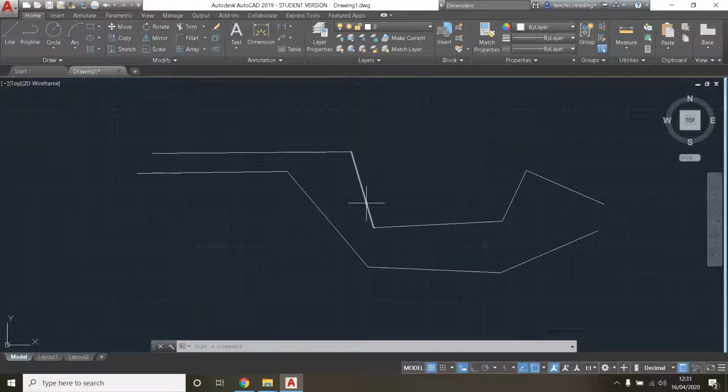Most often you'll be using a normal line. You will want to use a polyline if you are converting your 2D drawing into 3D. We usually use the polyline so that when we extrude, the result is solid. If you extrude a normal line, it is going to become sheets. Let's quickly delete what we just drew.